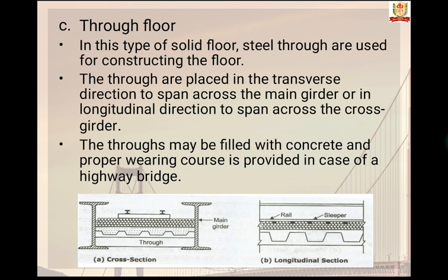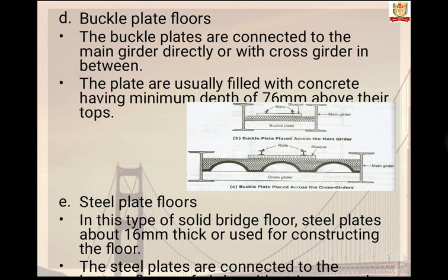Trough floor. In this type of solid floor, steel troughs are used for constructing the floor. The troughs are placed in the transverse direction to the span across the main girders, or in the longitudinal direction to the span across the cross girder. The troughs may be filled with concrete, and a proper wearing course is provided in the case of a highway bridge.